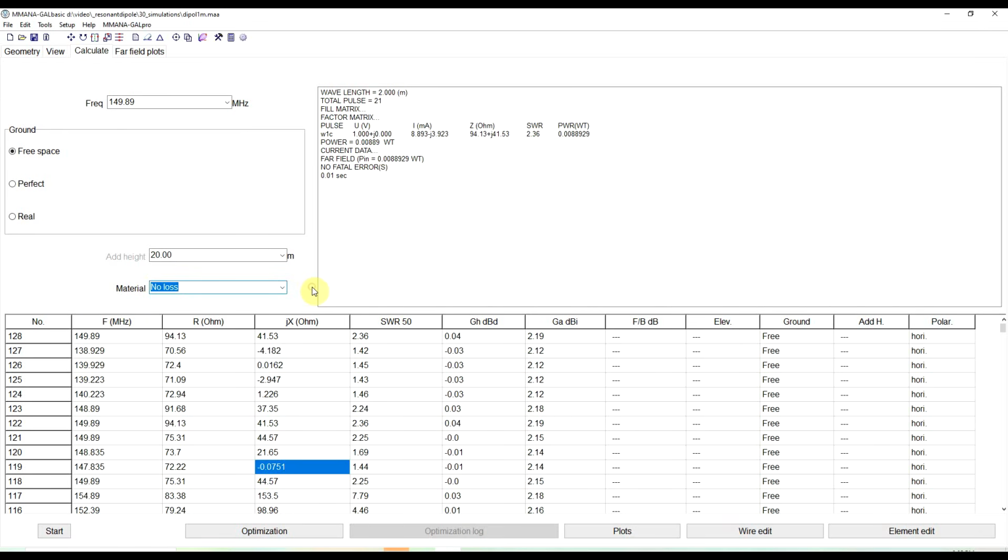Now, the other important consideration when talking about practical antennas will be the loss resistance. So not just the radiation resistance you get with an ideal material, but the loss resistance that you get with real materials. So this is material dependent, we have multiple materials to play around with, and it's also thickness dependent. So again, I ran the simulation for the multiple thicknesses with multiple materials.